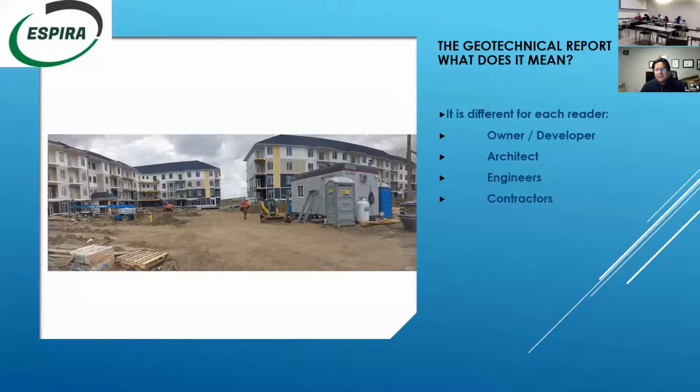Contractors. It is important for contractors to understand what type of cut and fill would be required to balance the site. Do they have to bring in fill, and what is the volume, where is the water table, prior to bidding on a project? Municipality. All new development permits require a geotechnical report. The municipality wants to make sure that if the land is close to a slope, the slope has been assessed, it's safe, and what the setback area is, etc.